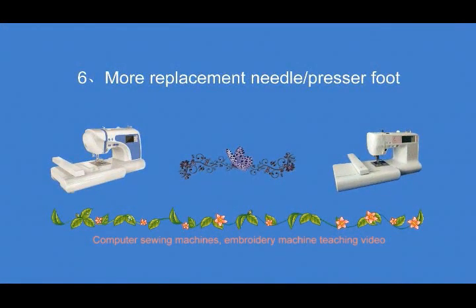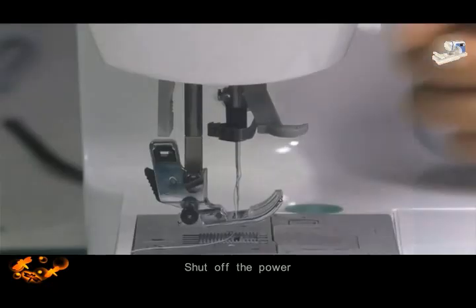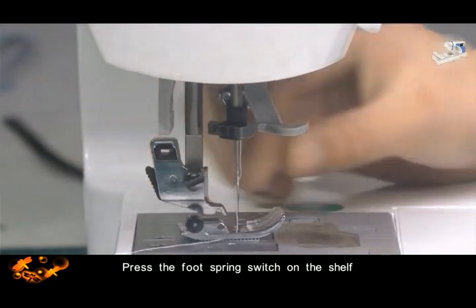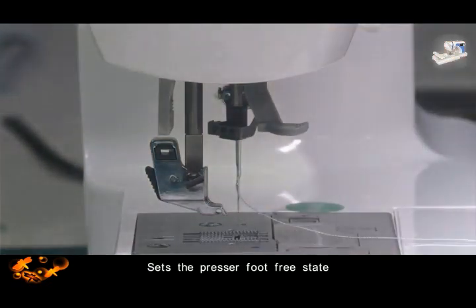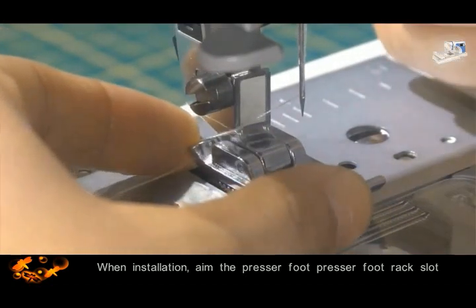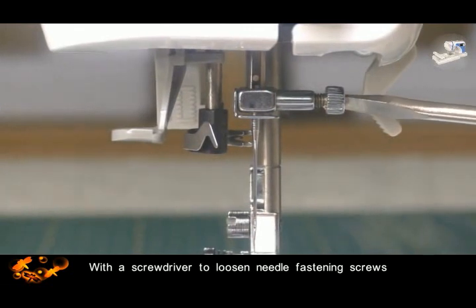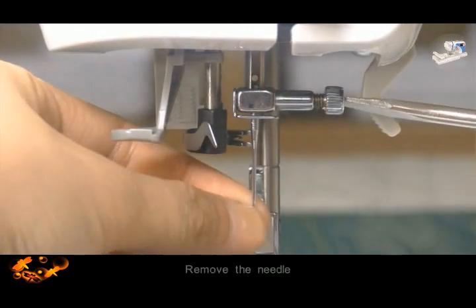Six. Replacing the needle / presser foot. Shut off the power. Press the foot spring switch on the shelf. This sets the presser foot to a free state. When installing, aim at the presser foot rack slot. Put down the presser foot lever. With a screwdriver, loosen the needle fastening screws. Remove the needle.